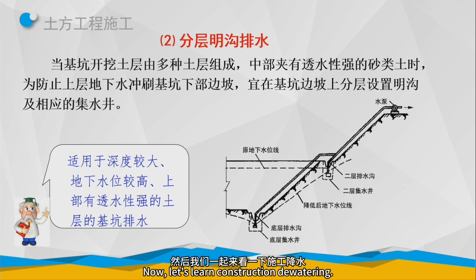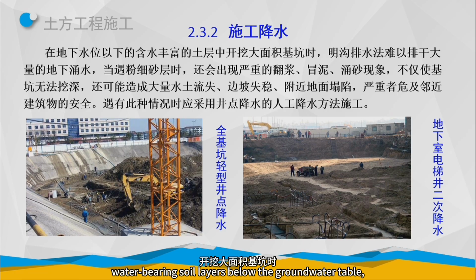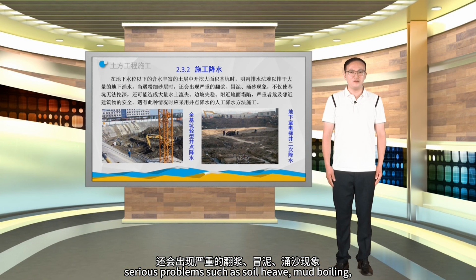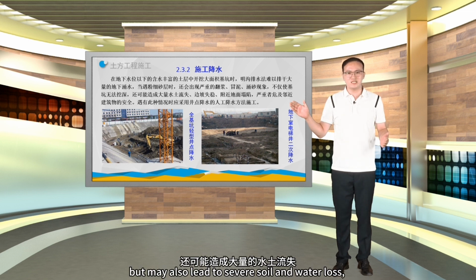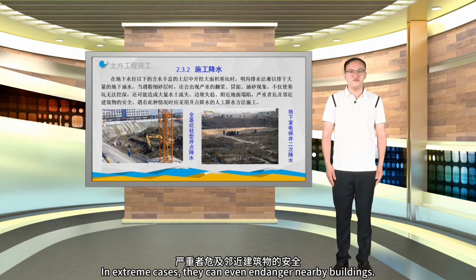Now, let's learn about artificial groundwater lowering. When excavating large foundation pits in water-bearing soil layers below the groundwater table, the open ditch drainage method often fails to effectively remove large volumes of groundwater inflow. When silty fine sand layers are present, serious problems such as soil heave, mud boiling, and sand boils can occur. These issues not only make it impossible to excavate the foundation pit to the required depth, but may also lead to severe soil and water loss, slope failures, and ground subsidence in surrounding areas. In extreme cases, they can even endanger nearby buildings.